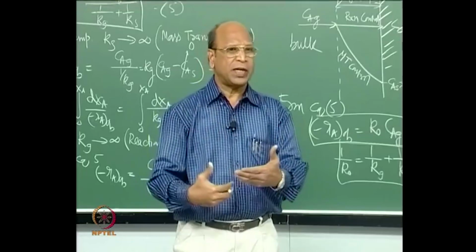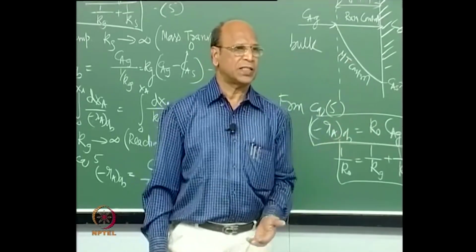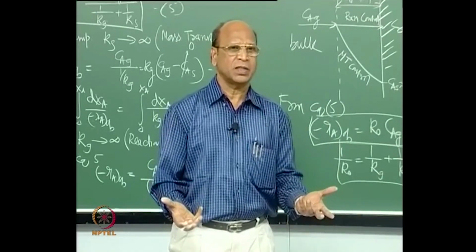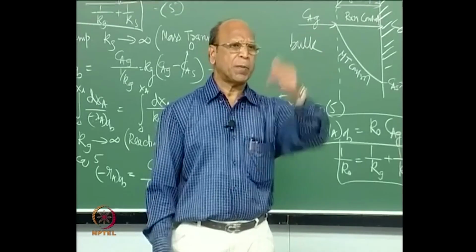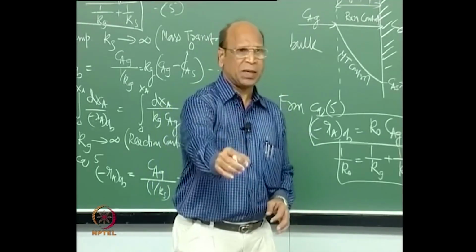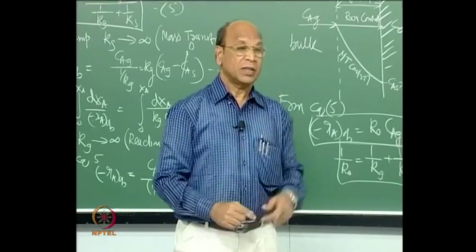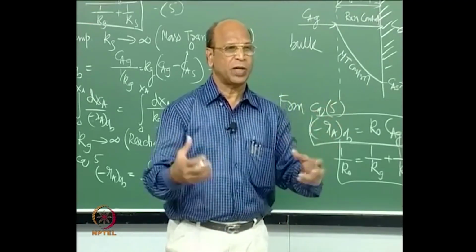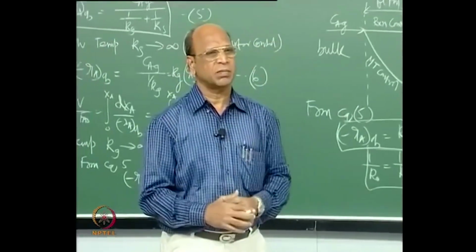So, if I evaluate data and get a set, and you evaluate and get a different set, what is the physical meaning of this? I may say that I have 15% dead space, you may come up with 30% dead space, but that system at those particular conditions must have only one set of values. That is why uniqueness in evaluating these constants is one of the biggest challenges in chemical engineering.